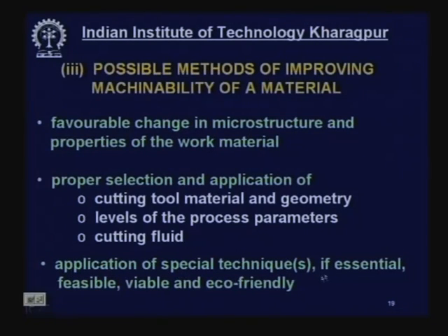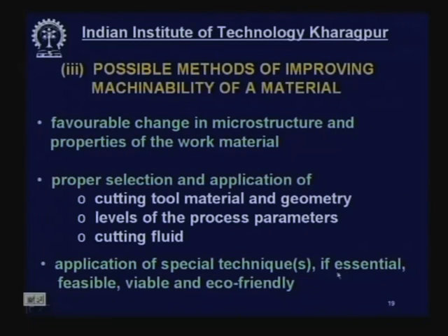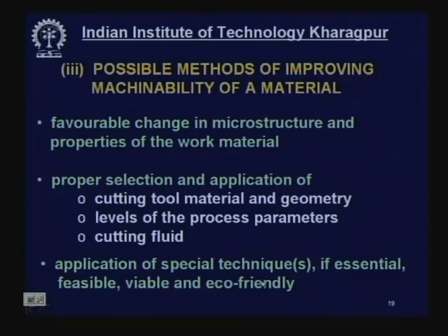Application of special techniques, as I told you, as and when required, like hot machining, cryo machining, stretch machining, dynamic machining, etc. Now, those should not be used everywhere. Those techniques should be used only if essential, where the machinability of certain materials is really very poor, like exotic materials, Nihard, Inconel, Monel, Hadfield steel, high manganese steel and so on. Not all techniques are always feasible; they have to be feasible and economically viable. Finally, special techniques should also be environment friendly; they should not pollute the environment and should not be hazardous to the operators.